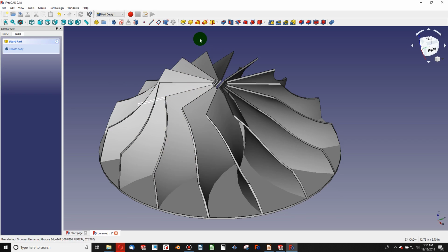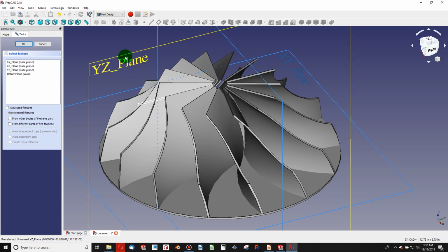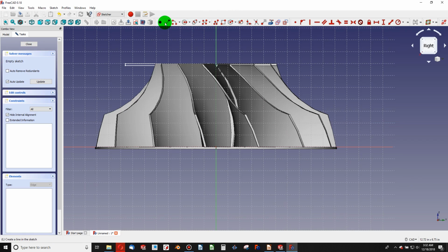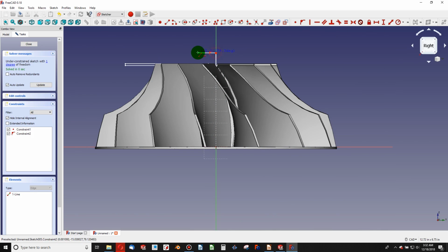Alright, so now let's add in a large fillet. Let's say on my YZ plane. And I'll do a revolve. And I'll do that by going onto my origin. Again, whoever can tell me how to clip the view so I can see my sketch better will save me a whole lot of problems. And I want to do the SolidWorks style 3-point arc, ends and rim point.